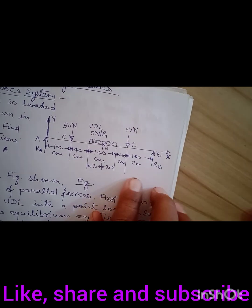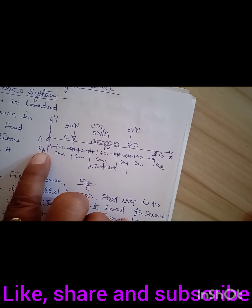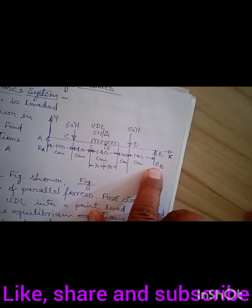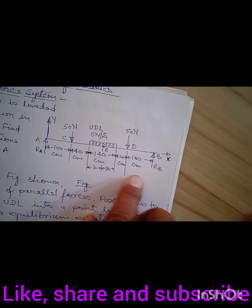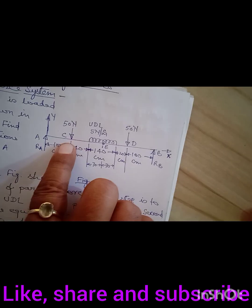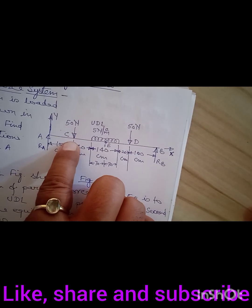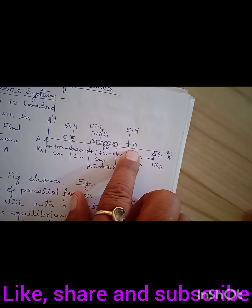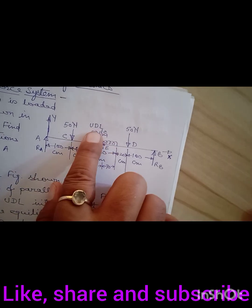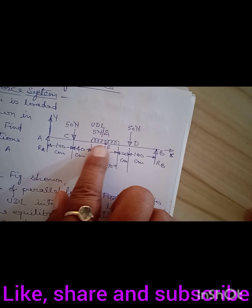Here you can see that this is point A. At this point, reaction RA is to be determined. At point B, reaction RB is to be determined. Now on this beam AB there are three forces: 50 Newton at point C, 50 Newton at point D, and one uniformly distributed load, UDL, at 5 Newton per centimeter rate.